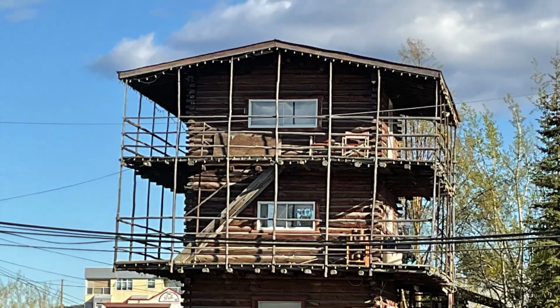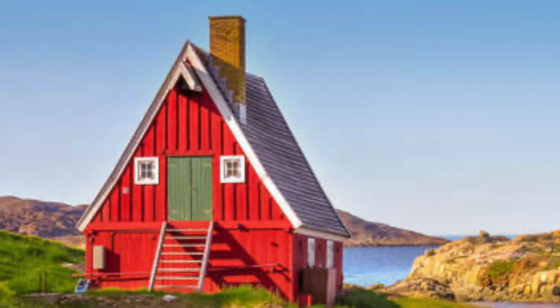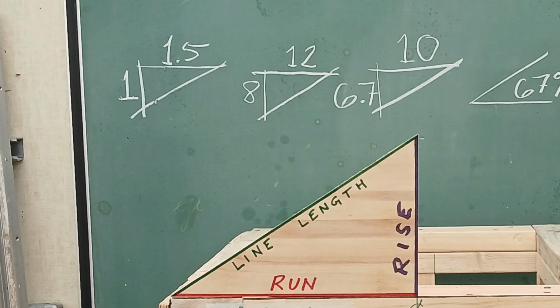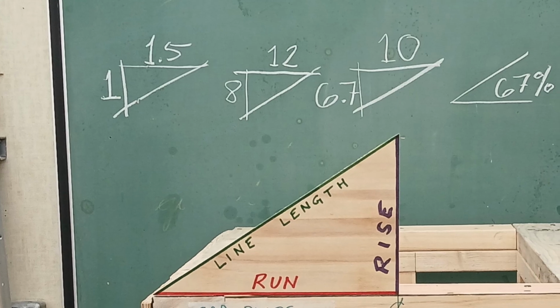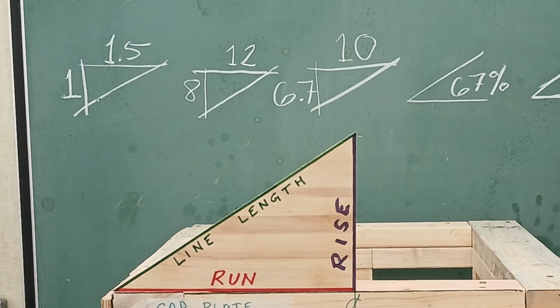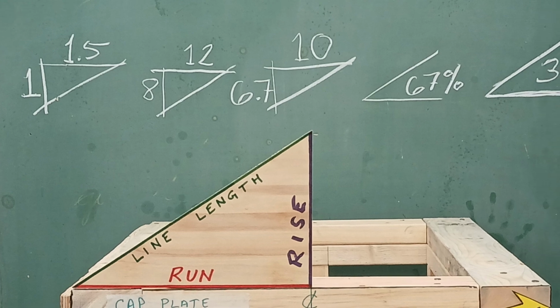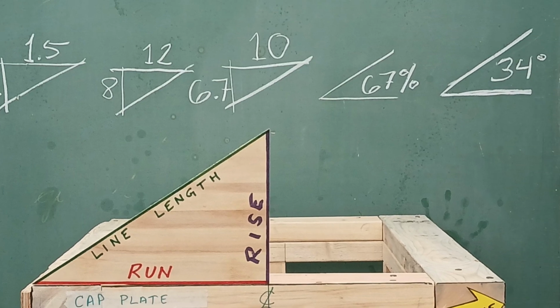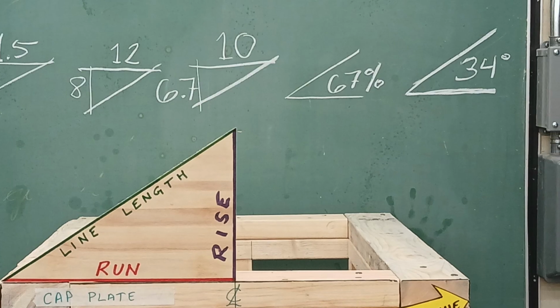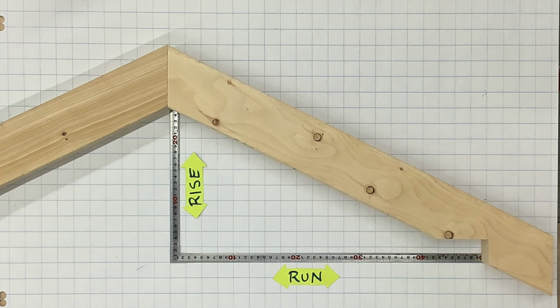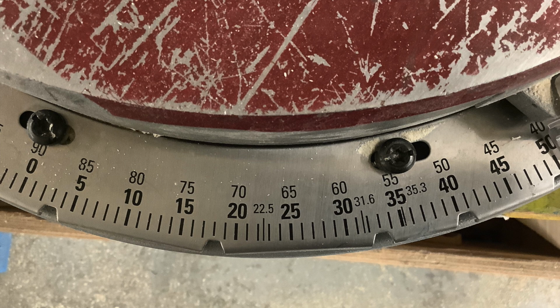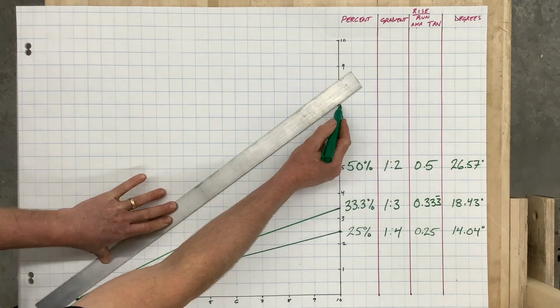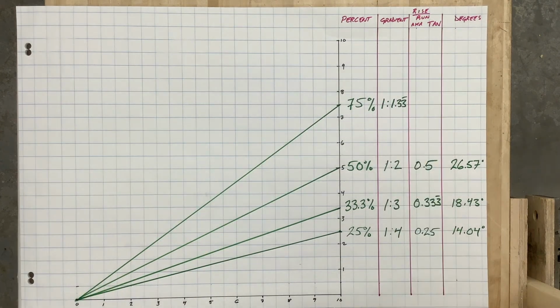Gable roof slopes can go from very low to very high and anywhere in between. The slope of the roof will usually be given on the plans using some variation of the slope triangle as shown here. Different parts of the world express the same slopes in different ways. Most countries use some variation of rise to run, but some places in the world also use degrees for roof slopes. We'll have a quick look here at how to interpret all the different systems used around the world to express roof slopes and how to move back and forth between them.